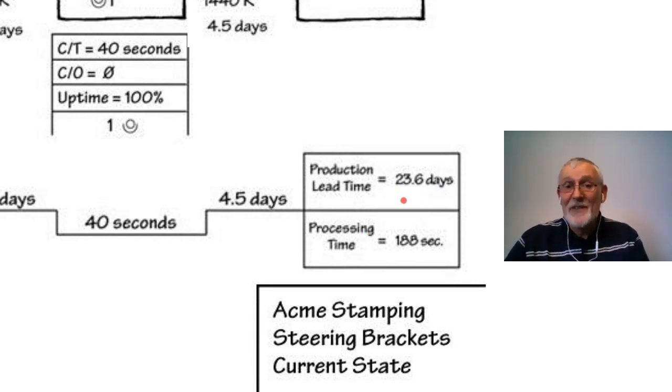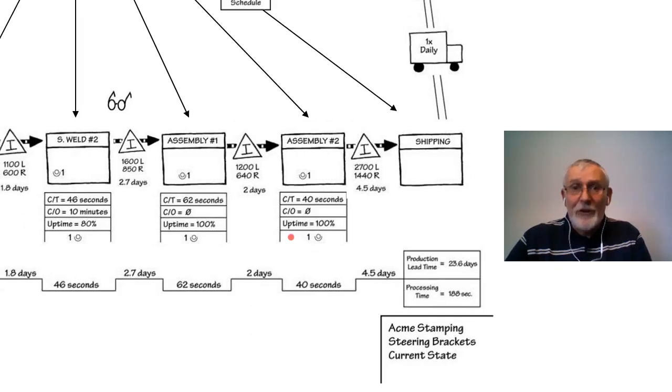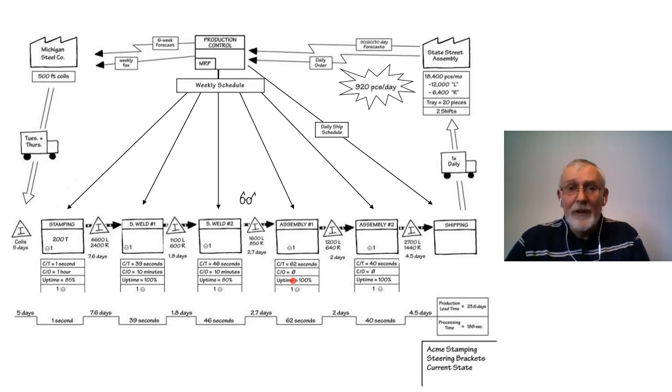Yet it takes 23.5 days for the inventory lead time, for the material arriving in to work its way through. So if a customer has a change, or if there's a spec change in the material, for example, we're sitting with 23.6 days of that customer's requirements in our works before we can introduce that new material change. Okay, so essentially what we've done is construct a current state value stream map.